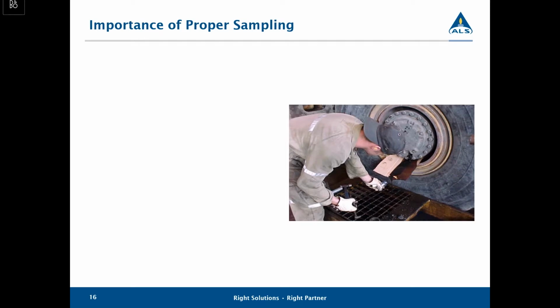Proper sampling is really important. I wish I had a picture of an aviation focused sampling process, but this is one that I use frequently on a heavy piece of equipment here. And I'll bring up some examples of how this is related to real world calls that I've received from aircraft owners. But here you can see the mechanic taking a sample after the fluid is flowing over a piece of cardboard.